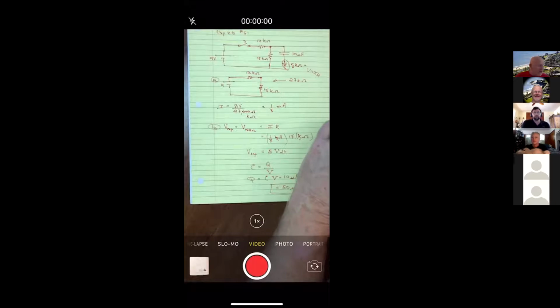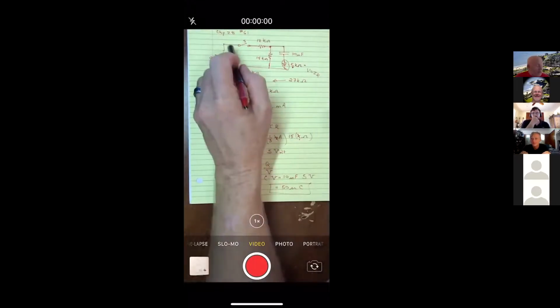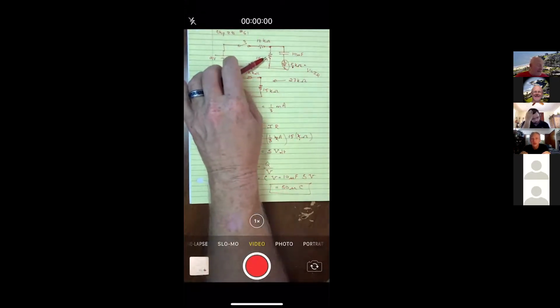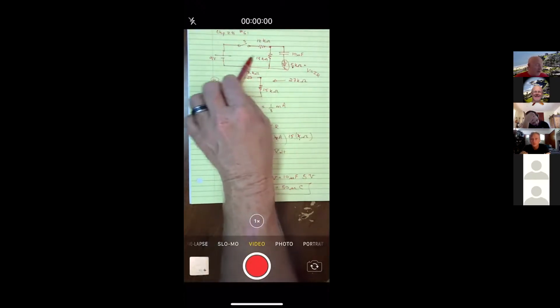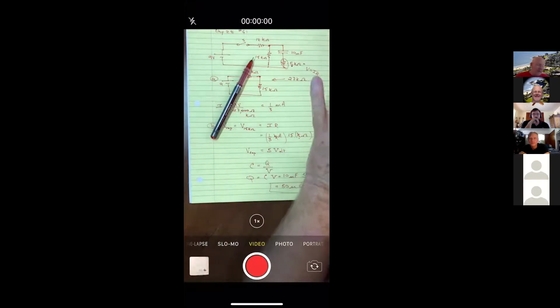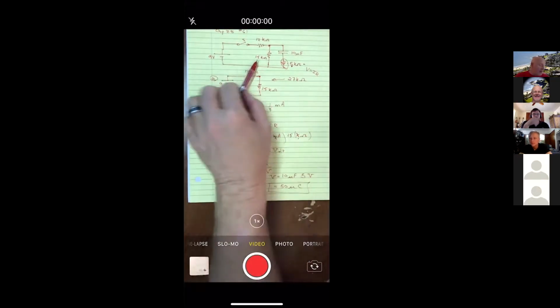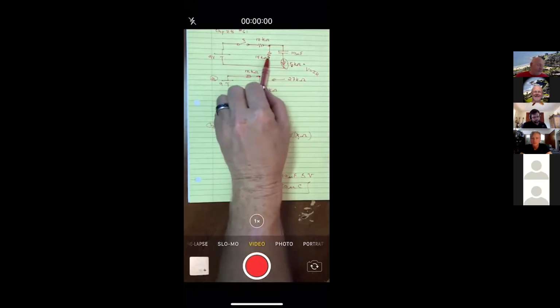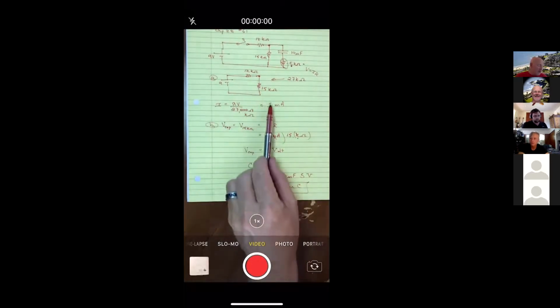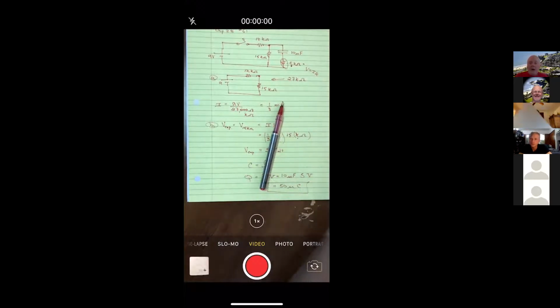Okay. So when you first close the switch, you're actually going to get a lot of current because not only does it go through here, but it's got to fill this up. And then that current goes lower, lower, lower. And it doesn't take long. For these values, this would probably take under a millionth of a second. Maybe not a millionth, maybe more, but definitely under a thousandth of a second. So this transient current is small time-wise. If you're talking about draining the battery, I would just ignore the transient current and say, look, the reason the battery drains is because of this 1/3 of a milliamp that is going on all the time, except for that first 1,000th of a second.